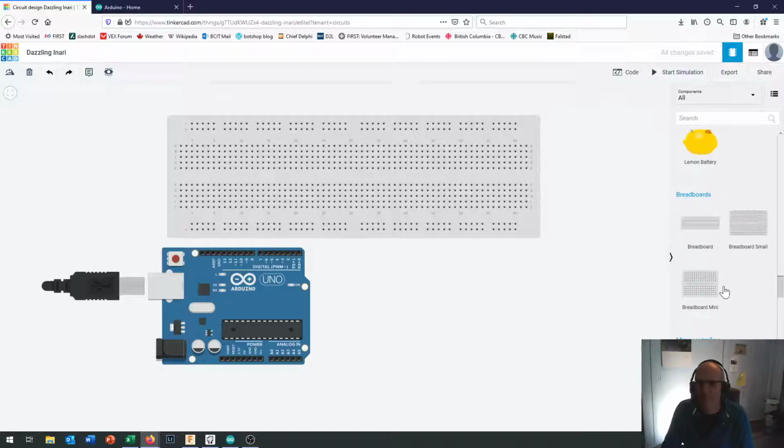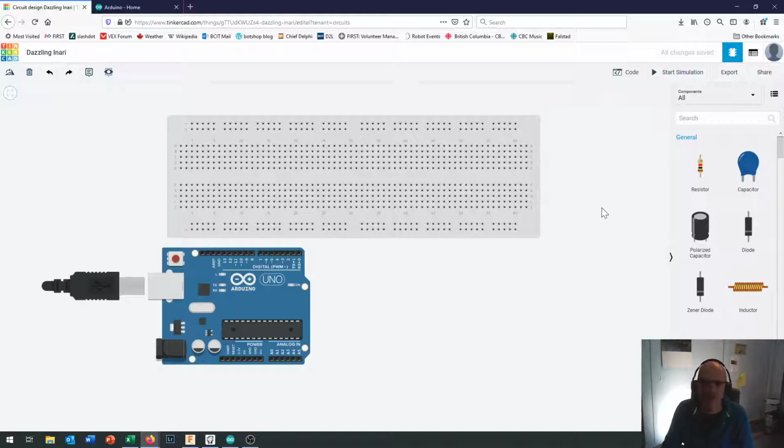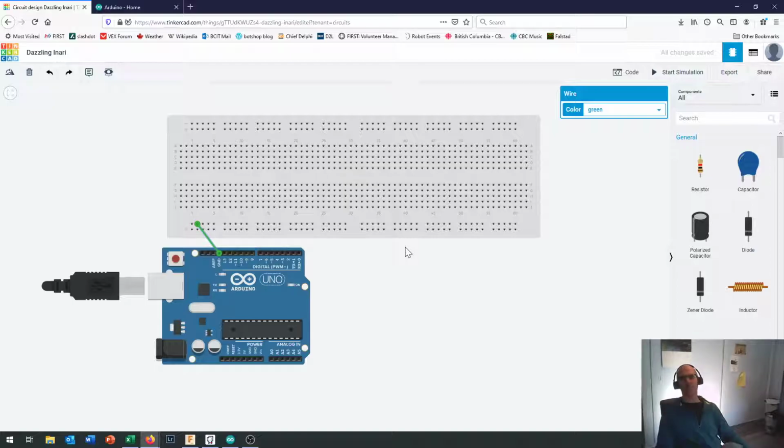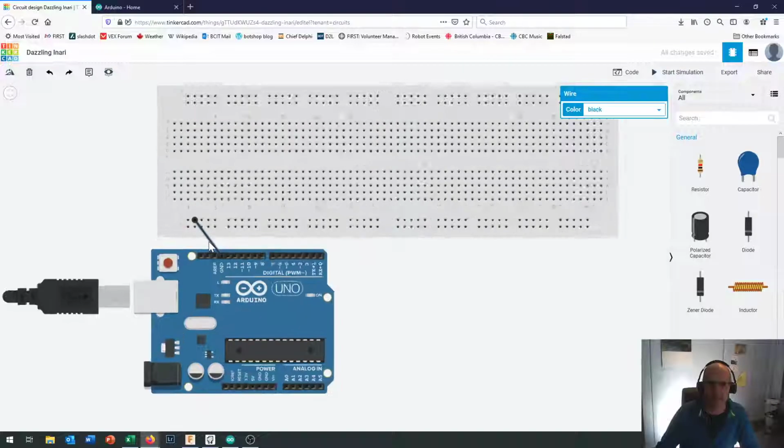And when it comes time to putting wires onto the board, that also goes pretty easy too. So one of the first things that we're going to do is we're going to wire this up by taking some power from our Arduino, and we're going to take a ground wire, and we're just going to run it. Oh, let's run it. Let's put it on the negative side. Good idea, you see we've got that little negative right in there, and click right there. Now, as our ancient rules of breadboarding passed down by the earliest breadboarders of the Renaissance, the electronics Renaissance, for some reason we have chosen that our ground will be black. So make your ground wire into a black wire right there.